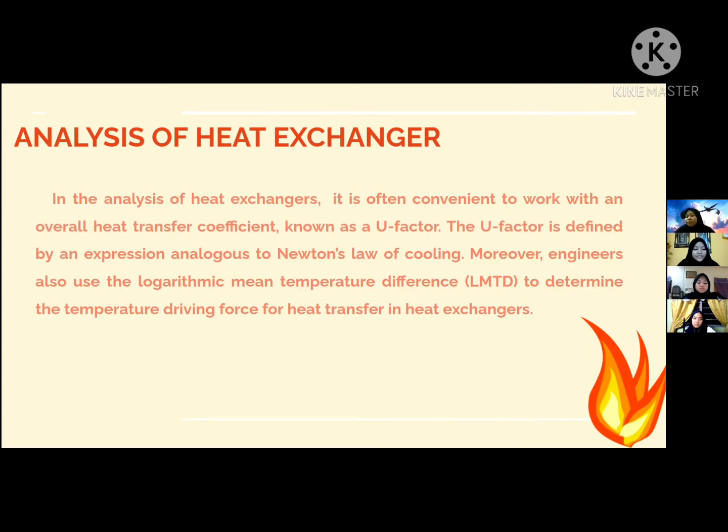Okay, now I will present the analysis of heat exchanger. In this part, I will present the formula used in the analysis of heat exchanger. In the analysis of heat exchangers, it is often convenient to work with an overall heat transfer coefficient known as a U factor. The U factor is defined by an expression analogous to Newton's law of cooling. Moreover, engineers also use the logarithmic mean temperature difference method, known as LMTD, to determine the temperature driving force for heat transfer in heat exchangers.